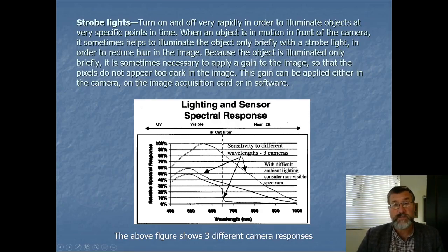They're selling the system. They sold it to various airports around the world to measure freight. San Francisco Airport, Amsterdam, are using the system now. But the upshot of all this is that when you're looking at an application, you want to think about the wavelength of the illumination you're going to use, and you want to look at the spectral response of the camera to make sure you get a decent response in that wavelength.